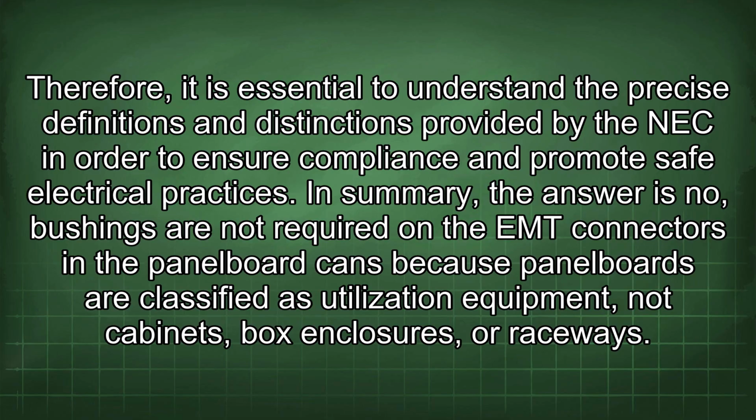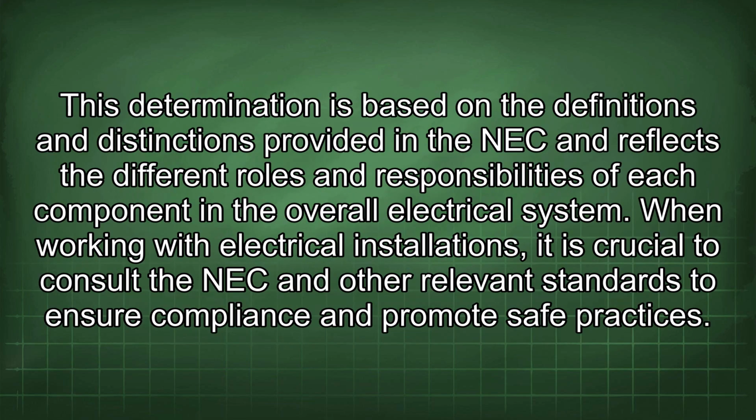In summary, the answer is no, bushings are not required on the EMT connectors in the panelboard cans because panelboards are classified as utilization equipment, not cabinets, box enclosures, or raceways. This determination is based on the definitions and distinctions provided in the NEC and reflects the different roles and responsibilities of each component in the overall electrical system.